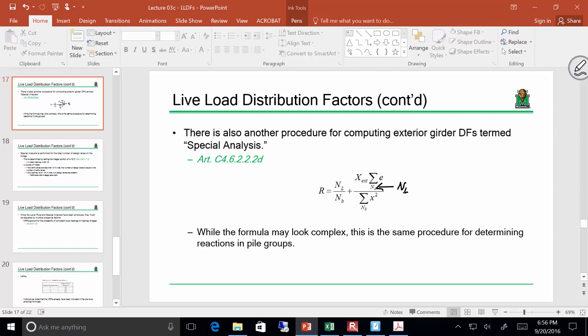I don't care what the paint on the road is. And it's a good point. There is a big difference between a traffic lane and a structural design lane. It's very common that a structural engineer might say that there's 4 lanes, and a traffic engineer might say, well, there's only 3 lanes. That's fine. From a bridge designer's perspective, we don't care about the paint on the road. There is a big difference between a transportation engineer's traffic lanes and a structural engineer's design lanes. We don't care.